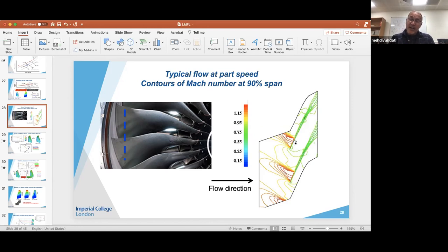So from an aerodynamic or acoustic point of view, it is much more difficult than a single isolated aerofoil like wings. But the easier part is that the mechanical mode shapes, because the blades are heavier than wings, the aerodynamics doesn't change the nature of vibration too much. But from the aerodynamics, they are a fair bit more difficult.